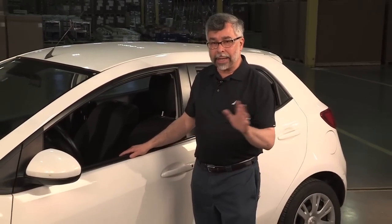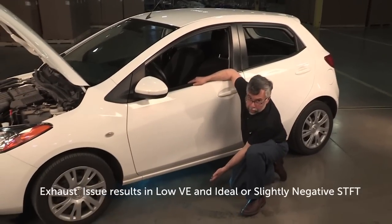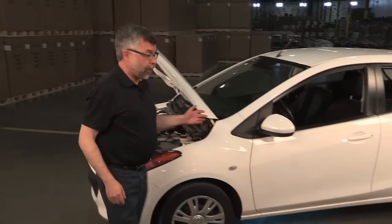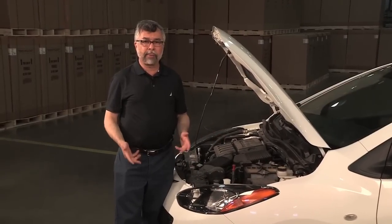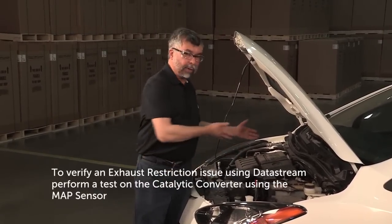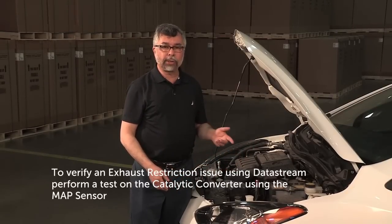An exhaust restriction would have VE test results of low VE and normal or slightly negative short-term fuel trim. This is caused by an exhaust restriction as a result of a plugged-up catalytic converter, or it could be as a result of carbon on exhaust valve throats. Proper VE requires the air to exhaust out. If there is an exhaust restriction, the volume of air required for the engine to create sufficient power will not be able to enter the engine. To verify that the exhaust restriction is the cause, you will want to test the catalytic converter.